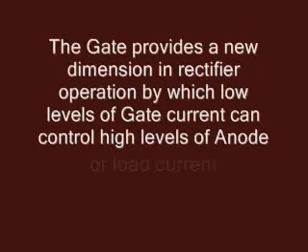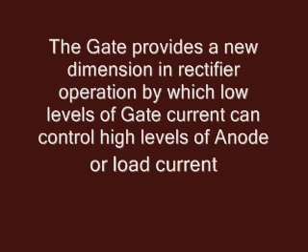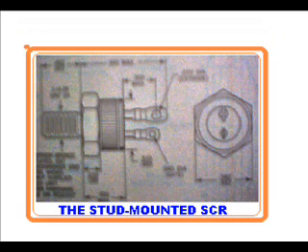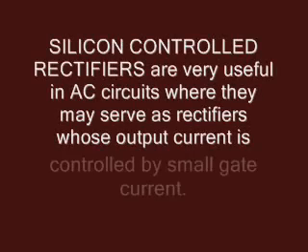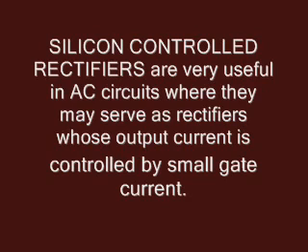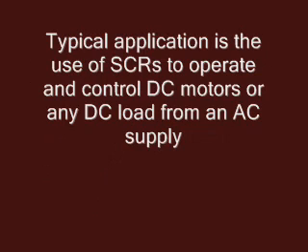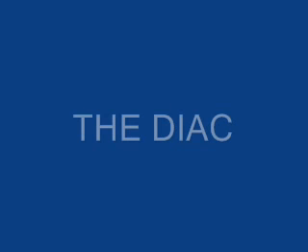The gate provides a new dimension in rectifier operation by which low levels of gate current can control high levels of anode or load current. The silicon controlled rectifiers are very useful in AC circuits where they may serve as rectifiers whose output current is controlled by small gate current. This typical application is the use of SCR to operate and control DC motors or any DC load from an AC supply. The DIAC.